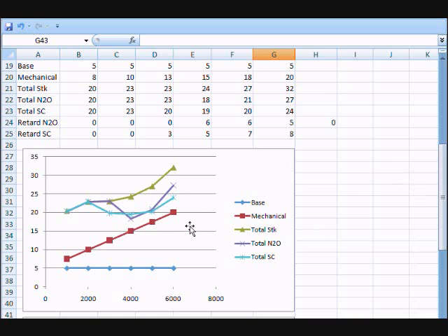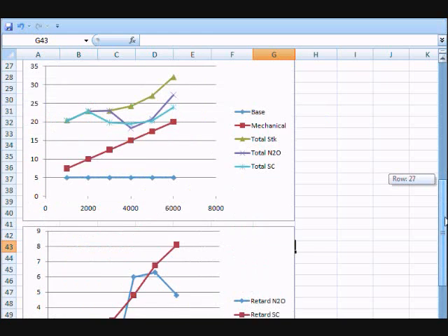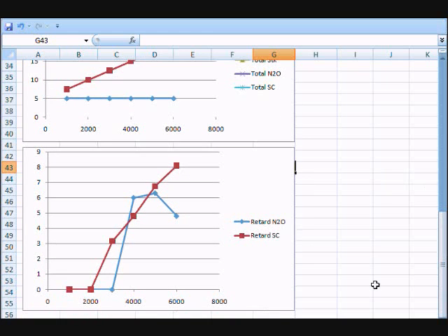And this might be a little hard to read, so I'm going to show you this in terms of just absolute retard. You can see for nitrous we want the maximum retard where we have the maximum volumetric efficiency, which is close to where we release the nitrous shot, and then we can have a little less retard in the higher RPM ranges. But for a centrifugal supercharger, boost builds with RPM, volumetric efficiency builds with RPM, and so timing retard needs to be proportional to boost, which will give us the best power results.